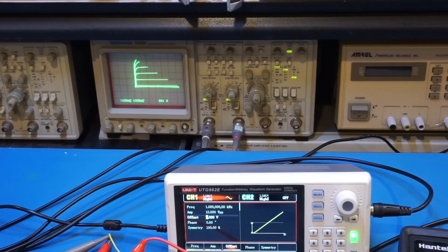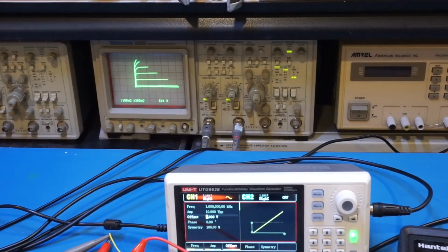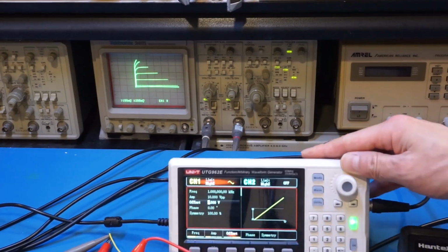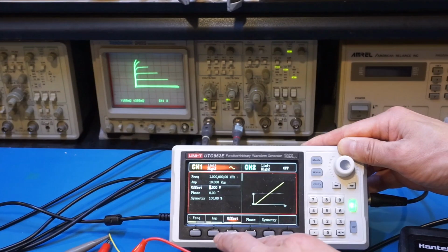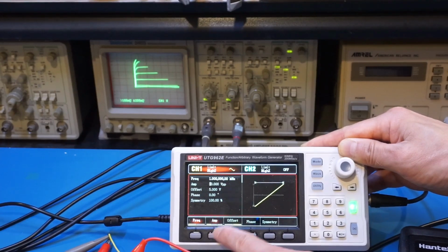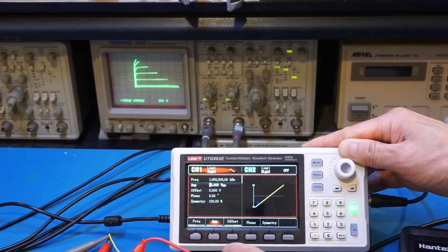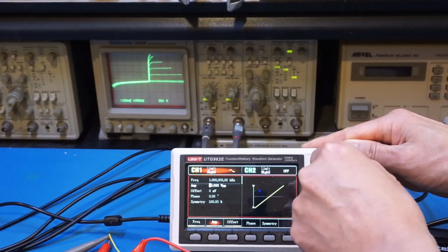With this 10 kilo ohm of base resistor and 1 kilo ohm of emitter resistor, we found ourselves do not have enough VCE dynamic range to extend the upper portion of the graph. Of course, in this case, you can do something a little bit clever because we know that the UT962E can actually generate a 20 volts peak-to-peak signal. So we will come back here to generate that 20 volts peak to peak. Of course, right now with the offset of 5 volts we cannot do that. We will change the offset to 0, and now we change the amplitude back to 20 volts.